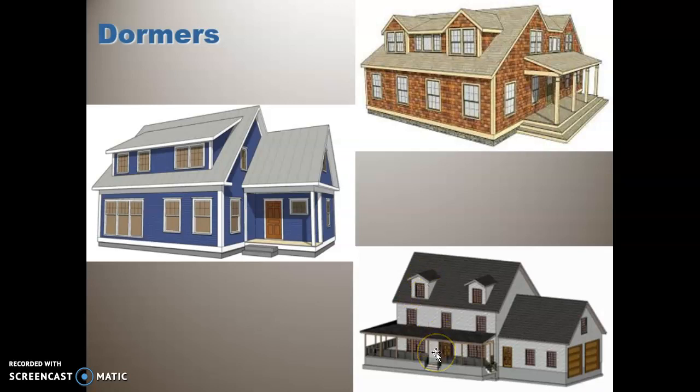You guys are going to find out when we get into thermodynamics, and you most likely know already, heat rises. So what this allows you to do is set up a little bit of a convection current in the house. When you open the windows up above, it draws the cooler air in. Heat obviously rises, leaves through the gables. So gables not only are aesthetically pleasing and functional, but they serve a pretty substantial purpose when we start designing our building.